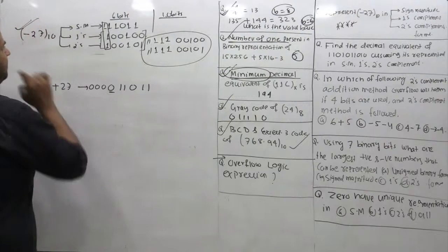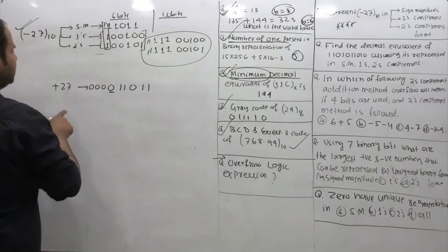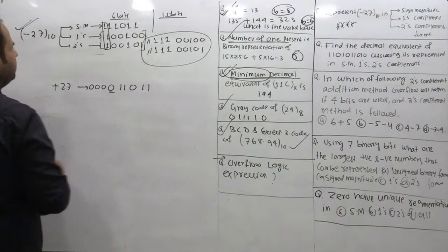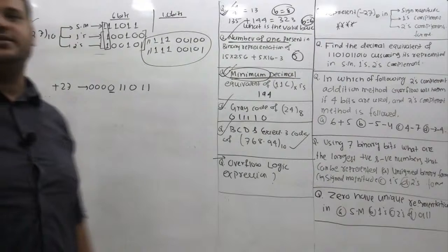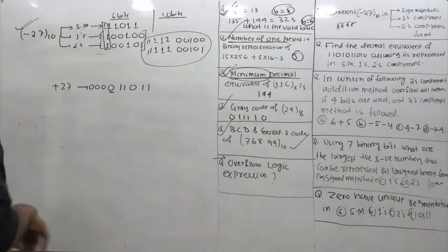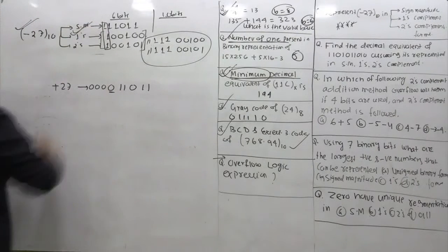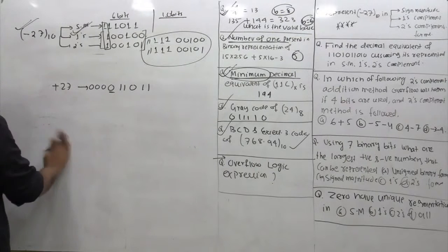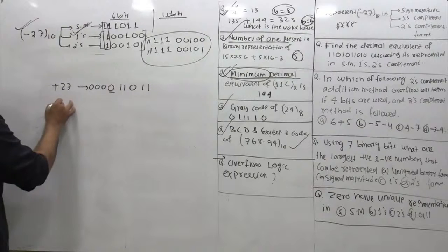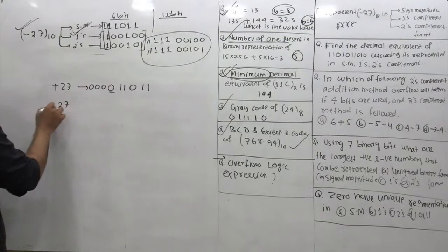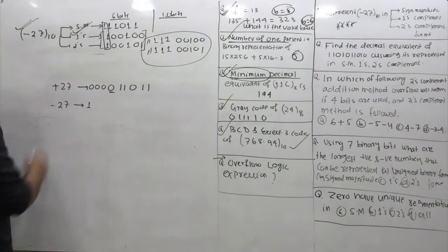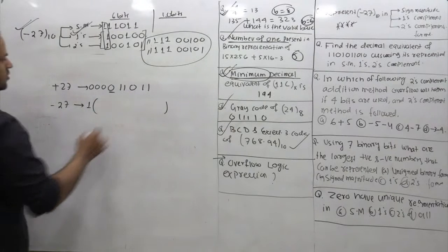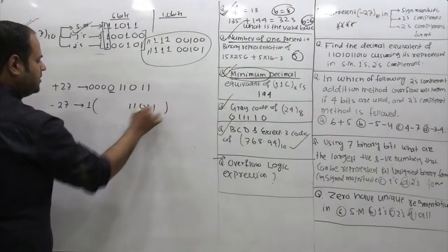But if I ask the question, this logic I said is for 1s and 2s complement. In 1s and 2s, if we copy the sign bit any number of times towards left, then there is no change in original value of numbers. But what about sign magnitude form? Very simple logic. So if this is plus 27, what is minus 27? Because it is minus, this bit should be 1. Then the rest of the bits should indicate 27. So 27 is 1, 1, 0, 1, 1.